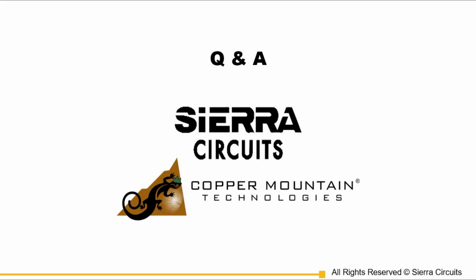Next question: have you used TDR to check impedance of vias? I haven't done that in years, but yes, it can be done. Let's see. The change in dielectric constant in the Z direction from that for the X and Y direction. Well, I think you're talking about the effective dielectric constant, because you're no longer going along the top of the board, you're actually going through the dielectric. I think that must be what you mean.